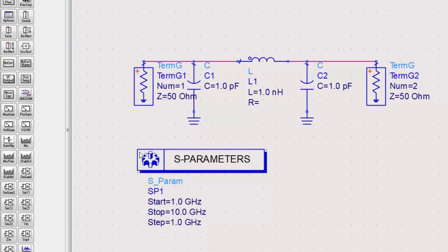You can find the simulation parameter controller from the S parameter library palette. If I connect it up this way and run an S parameter simulation, num1 is going to be port 1, which is the excitation point, and num2 is set for port 2, which is the measurement point. Great! The setup is complete for the S parameter simulation. I left everything at default, but you can change it if you want. Right now the capacitor and inductor values are 1 picofarad and 1 nanohenry.